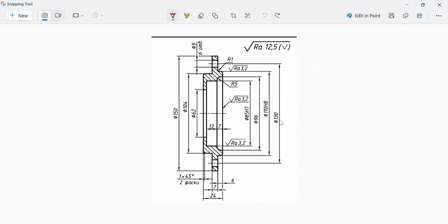These are diameters. Our aim is roughness. This means fillet of radius 5 and 1. This means hole. There are 6 of them, and they all have a diameter 9. This means a chamfer, and we're going to use this as a guide to bring our model to life. Not literally. So let's begin.